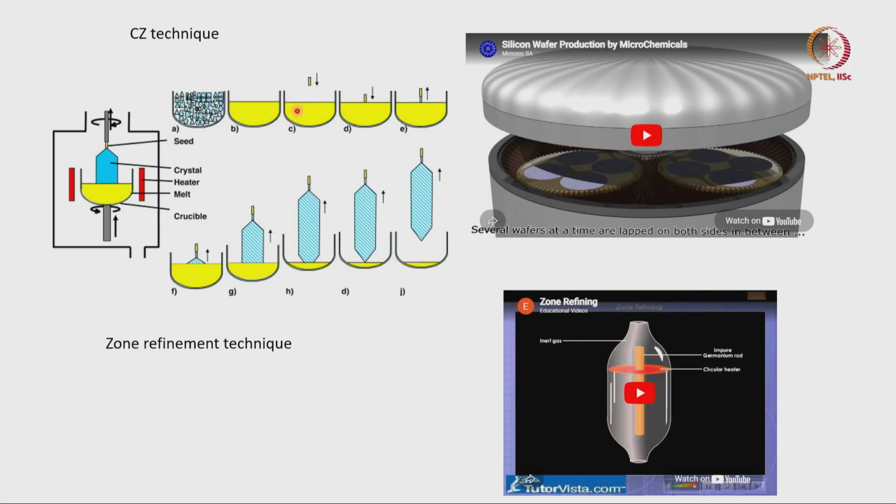You don't always need to melt, right. So in this process you are coming to a single crystal from the melt phase, but you don't always need to melt. You can come from one phase to another phase, a high temperature phase to a low temperature phase, something like iron for example. I can just heat it to a higher temperature phase and then cool it down to a lower temperature phase, and make the wires more ductile, let us say, and then draw iron wires in a shape that I want and then cool it down to a low temperature phase. So I need to learn about phase transitions.